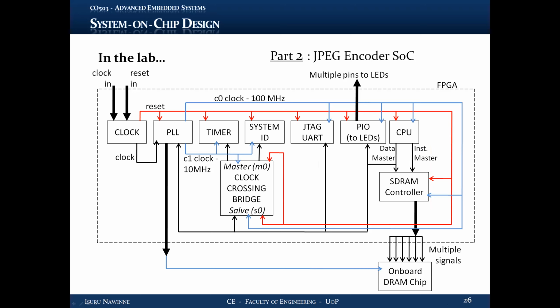If you use the very same clock signal for the on-chip components as well as the off-chip memory, you encounter something called clock skew. Clock skew is the rising and falling edges of the clock being delayed when transmitted through a very long copper wire to an off-chip component, right?